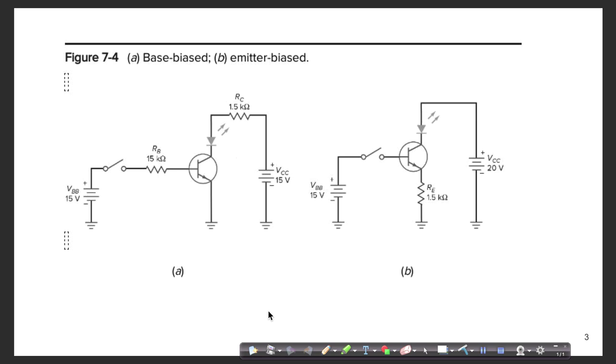Now, the real difference between the two circuits is that the base bias circuit, which is lab experiment number 4 in the current version, is very beta unstable. The actual collector current and collector to emitter voltage vary a lot with the beta, which is a highly unstable value.